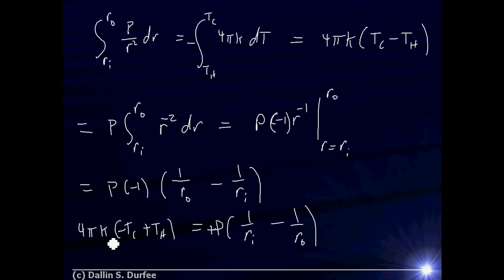More thermal conductivity. Iron is very thermally conductive. That makes for more power. If I have a bigger outer diameter, bigger outer diameter makes this smaller. I subtract off less, right? A larger outer diameter means basically it's like more insulation, right? Bigger inner diameter acts like less insulation.